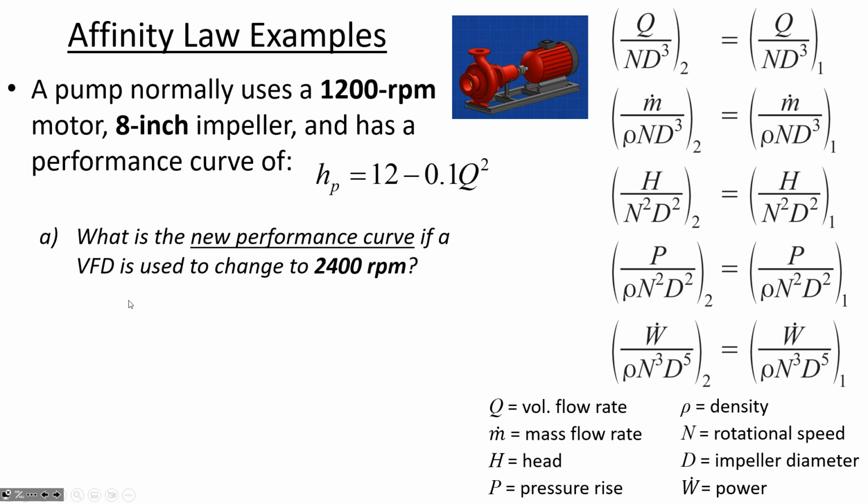But what we want to know is, what if we change the rotational rate of this system by using a variable frequency drive? Has anybody heard of a variable frequency drive before? We kind of take it for granted that electric motors can be turned up and turned down really easily, but it turns out that's not the case. A lot of motors are only intended to operate at a certain fixed rotational rate. And so for some pumps, you have to get a really expensive, complicated piece of equipment to change the speed that the motor is rotating at.